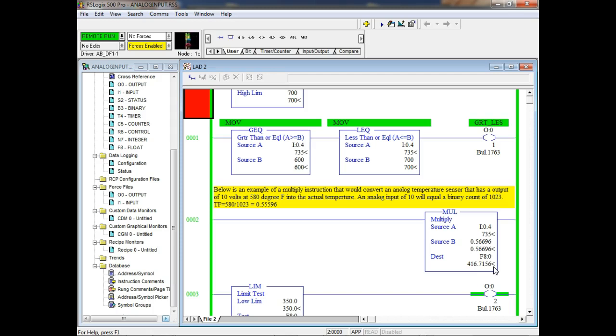So the Siemens, I'll try to play around with that a little bit. The 1200 we have also has an analog output on it. This doesn't have an analog output. This has an analog input. But it does basically the same thing. It's going to take an analog input and convert it over to a binary number that gives you a rough representation. It's not going to be perfect. The more bits you have on your A to D converter, the better the resolution, right? Does that make sense? Yeah.